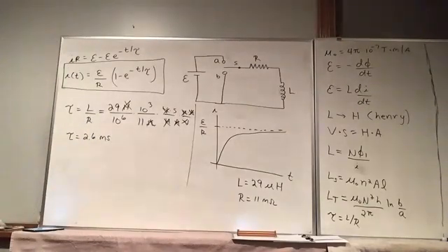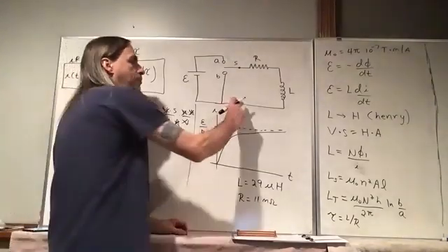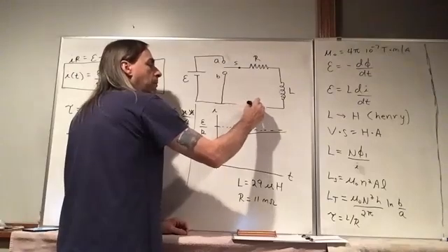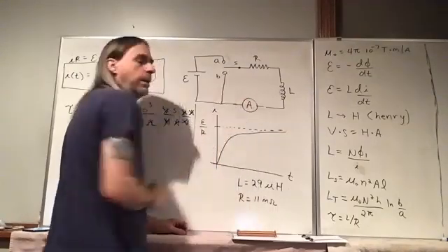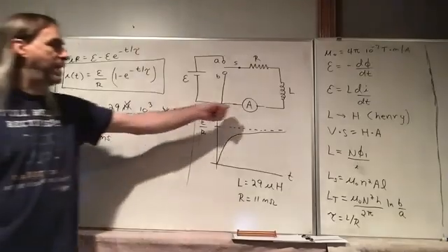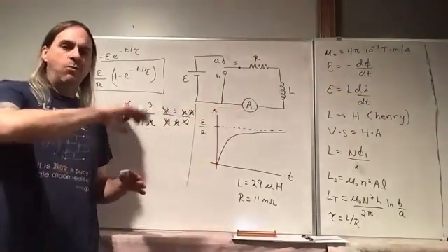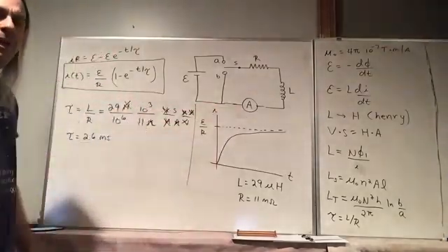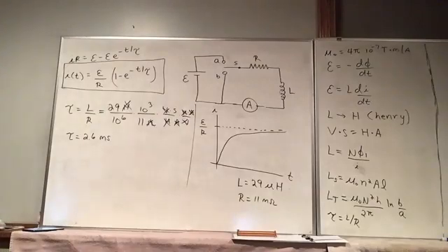And again, that's why I said if you were to wire this up with an ammeter here, and you flip the switch and just watch the ammeter, you're not going to see it rising slowly like you did in the capacitor lab. You could see it rising slowly with a large capacitor. In this case, that's not going to happen.